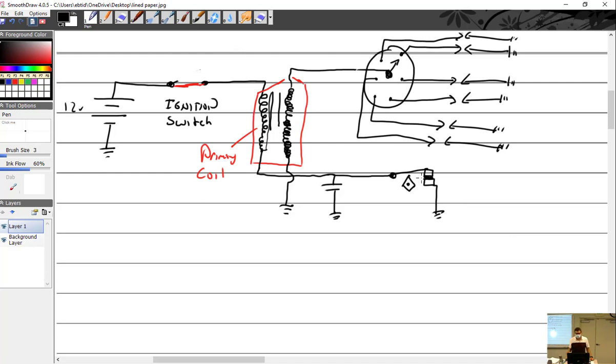And when it starts to open them, the current flowing through is going to want to jump this, but it can't because we have a capacitor here. And so as soon as we add some resistance to these points, the capacitor is going to look like a better path to the electrons, so they will back up, run into the capacitor. That's good. That allows the points to open. When the points open, the capacitor is charged. There's no way else for this current to flow through the primary. So it does what? Quickly, slowly, medium, as fast as possible. Right now. Violent, as instant as it can.